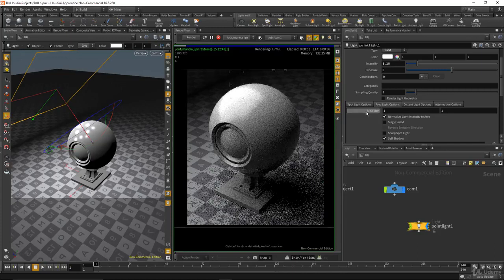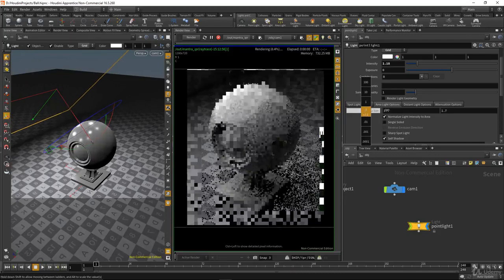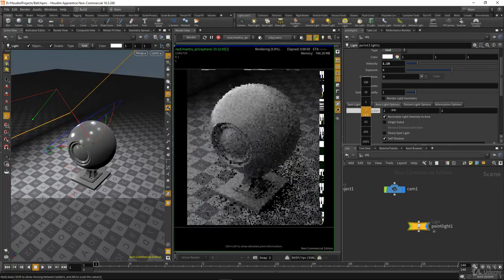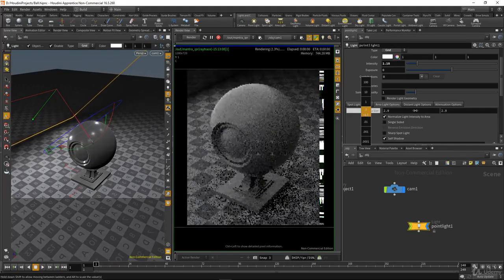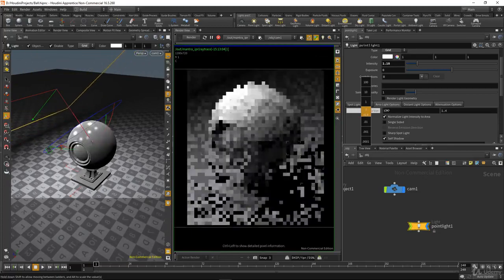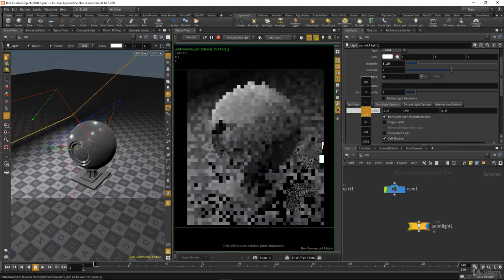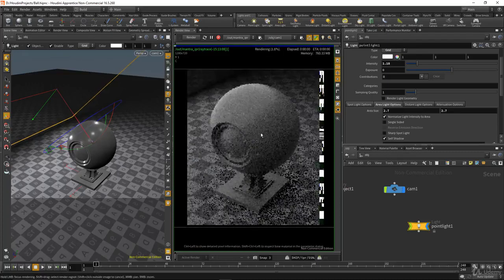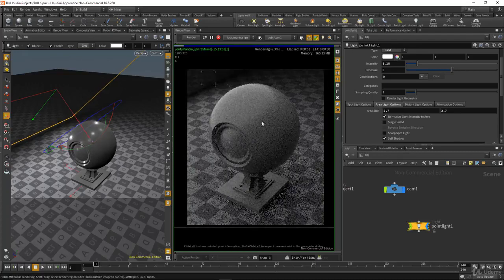If you hold the middle mouse button and move that, you can increase it. As you see, I am making the rectangle bigger, and at the same time, as you see guys, the light is fading in the viewport, so it is distributed in all the scene.